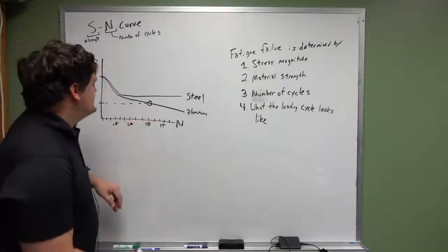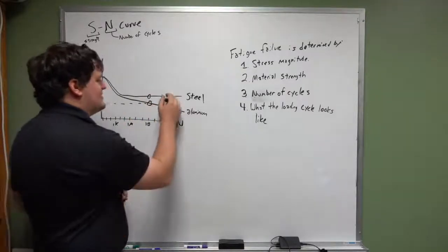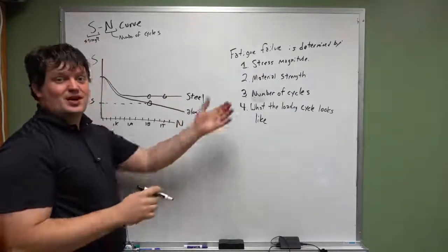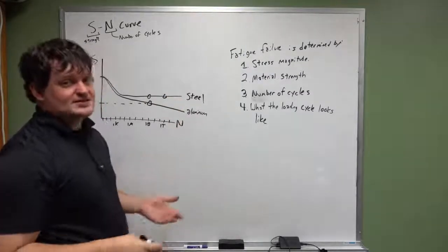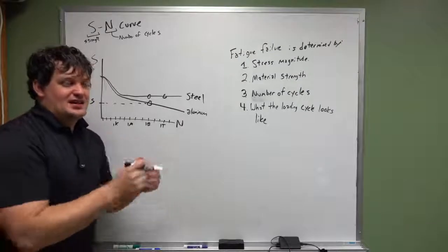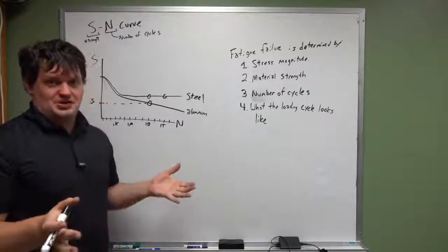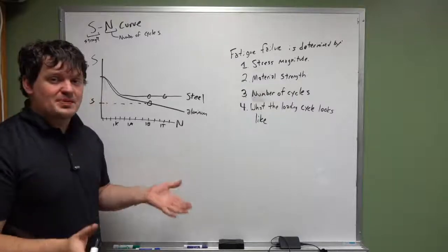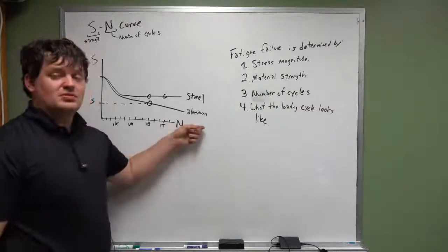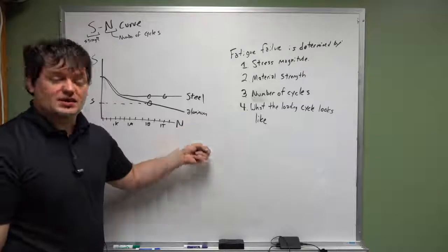Whereas with steel, you say I want it to go 1 billion cycles, well that's the same value as a trillion, as a quadrillion. Because it has that knee, it has that malleability inside of it where it can handle crack propagation. The crack stops propagating at some point. In aluminum, the cracks continue propagating indefinitely.